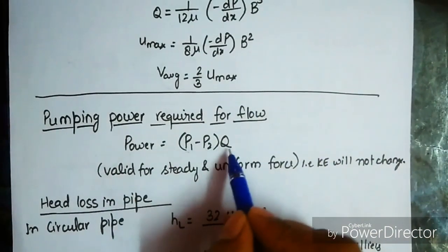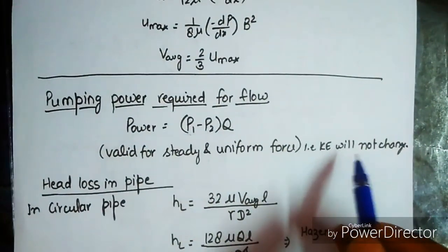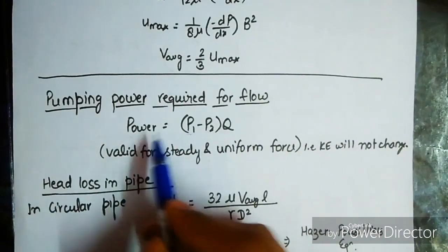Difference in pressure into discharge. This is valid for steady and uniform flows, that is, kinetic energy will not change. In those cases only we can apply this power formula.